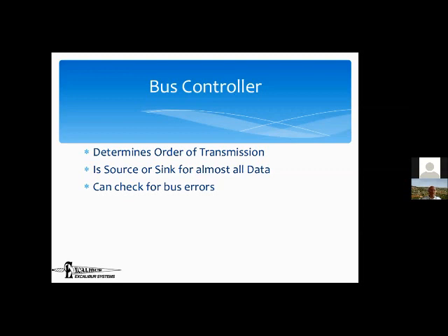One is, since the bus controller has to now speak directly to each of the RTs or terminals or boxes, it's in direct communication with all of them. And in 1553, they said, all right, as long as I'm in direct communication, let the data always flow through the bus controller. So the bus controller would send data to each of the RTs, and it will receive data from each of the RTs.